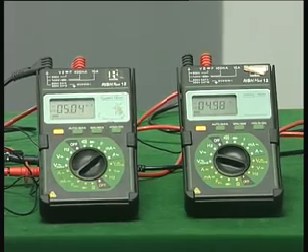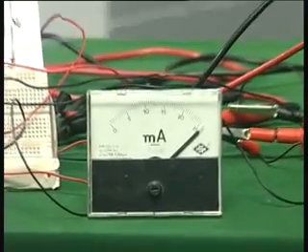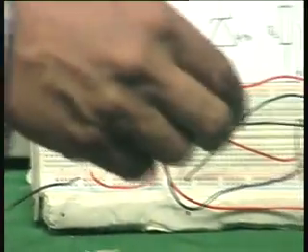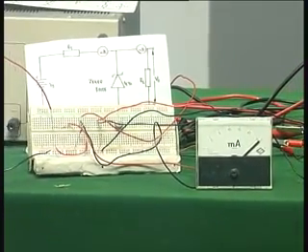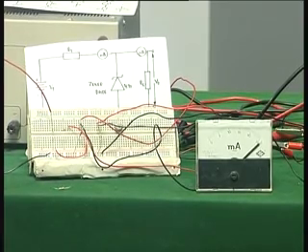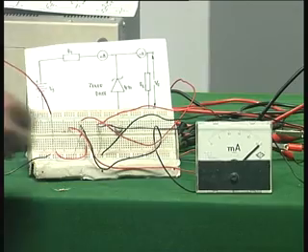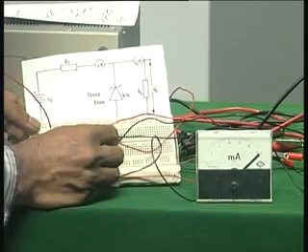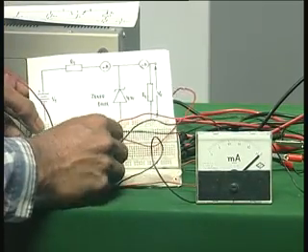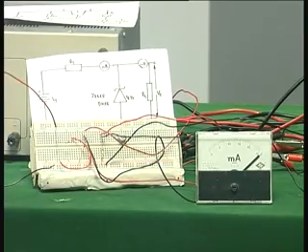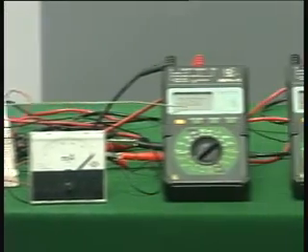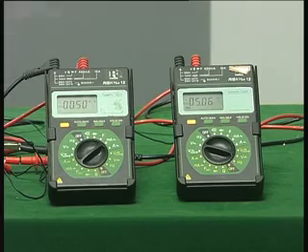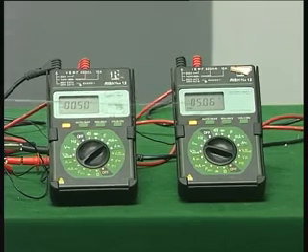But the input current is nearly more than 25 milliamperes, so the rest, about 20 milliamperes, will be flowing through the Zener diode, right. Only 5 milliamperes flows through the load. Similarly I can still increase the load resistance by removing the 1k resistor. Let me connect a 10k resistor. Now you can see the current has become 0.5 milliamperes, 500 microamperes, and the voltage is 5.06, very close to 4.9.